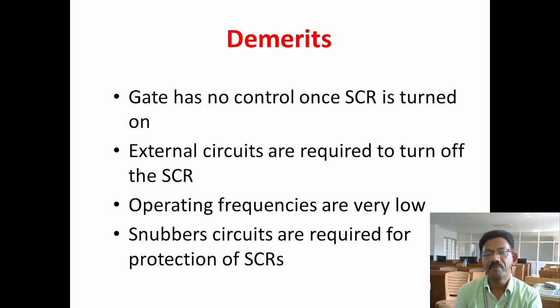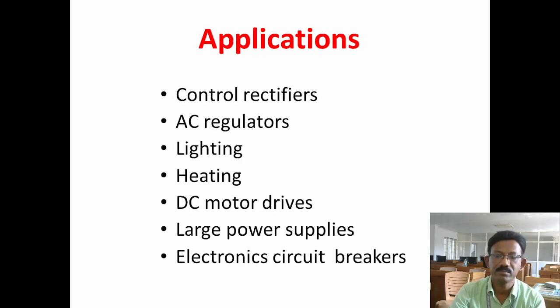Then operating frequencies are very low. That is why these SCRs are suitable for low frequency operations only. Then snubber circuits are required for protection of SCRs. Extra circuits are required for protecting the SCRs from switching surges as well as high voltage and high current.